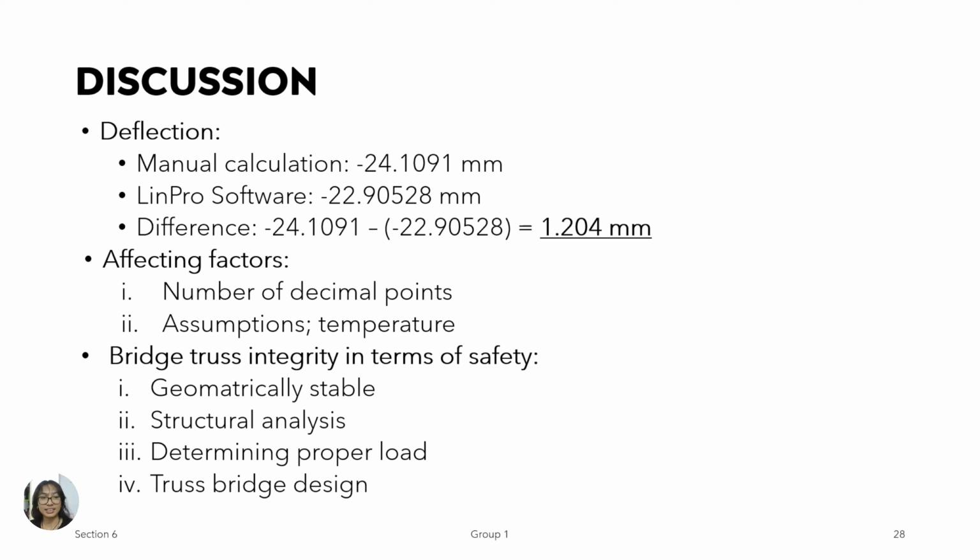Now, other factors that I did not put into the slide are structural stiffness, pre-stress loss, environmental temperature, and concrete shrinkage and creep. They may also affect the deflection of the bridge frames. However, it is quite insignificant.